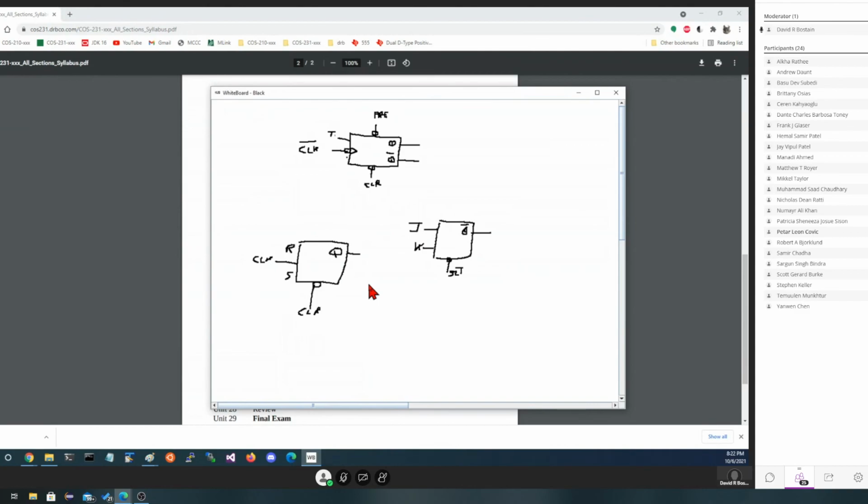Important thing here is these happen over time. They're not like the AND gate where we applied a signal and we always thought of it as having an output right now. We need to know something about this one. What state is it currently in? What happens on the clock later, or what happened the last time we saw a clock? So we start to care about propagation delay, hold time, setup time, maximum frequency. So just put your thinking cap on and think about that. Now I would review all these slides because I think they all contain data you're going to want to remember.